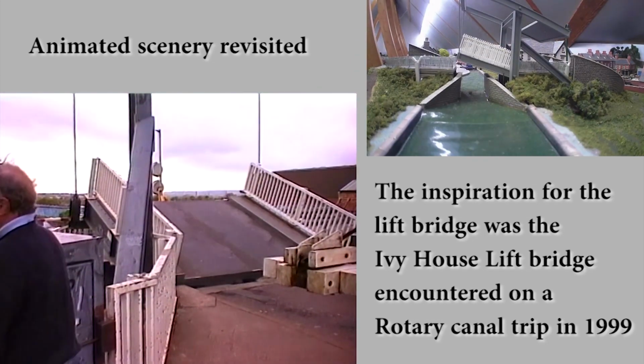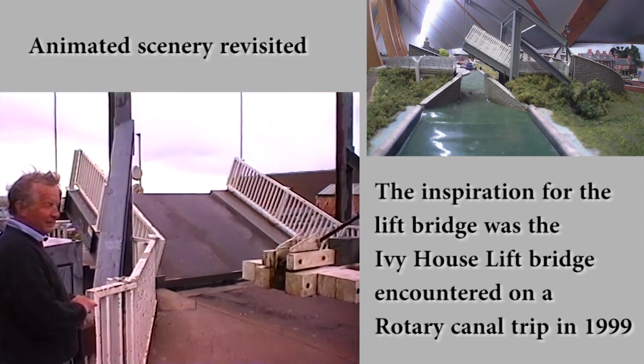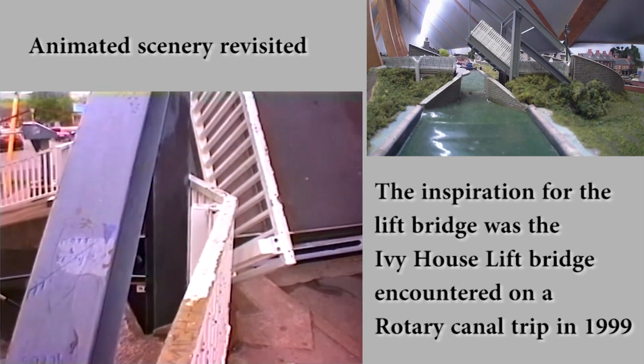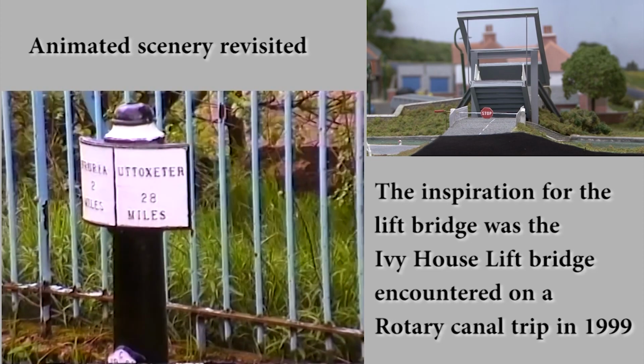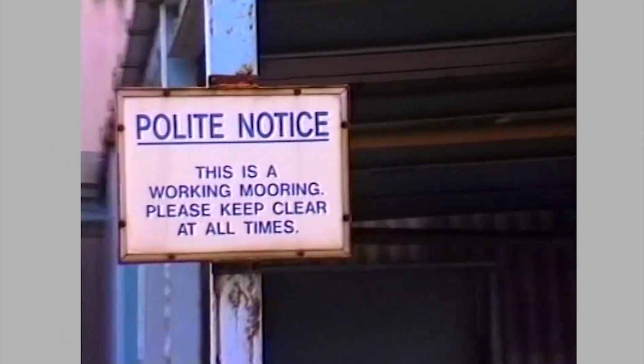The bridge will not lift unless both the road barriers are properly down, and the barriers will not lift unless the bridge is fully down, and the operator cannot remove the key unless the bridge is down and the barriers are up and the lid of the box is closed. Needless to say, we experience no problem at all.